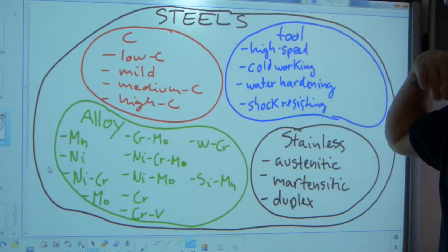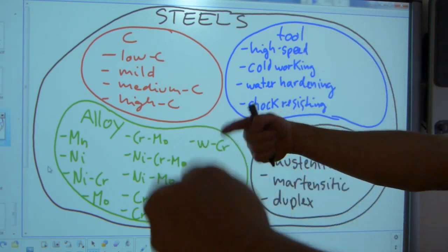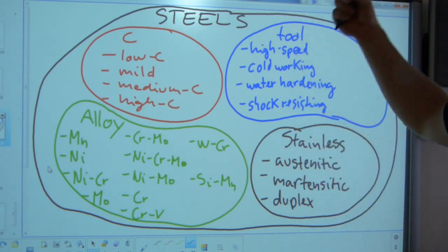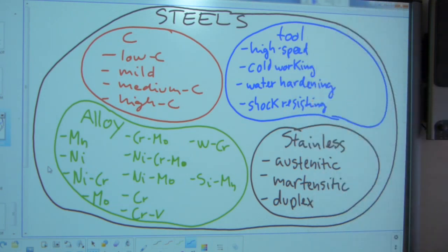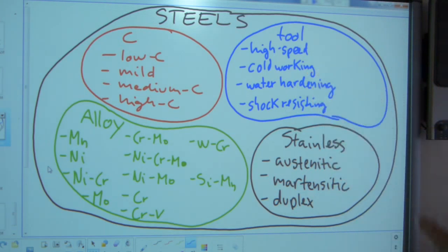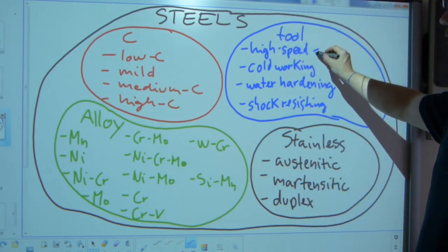High-speed tools or high-speed steels, as they heat up, working on a high-speed rotating workpiece, they do not soften, they do not dull, and they do not lose their edges. None of this stuff is weldable, so completely forget about it. These tools cannot be successfully fixed because they are special alloys, and because of their carbon content as well. In welding they might stick together barely or temporarily, but it's not going to be holding with any amount of strength.